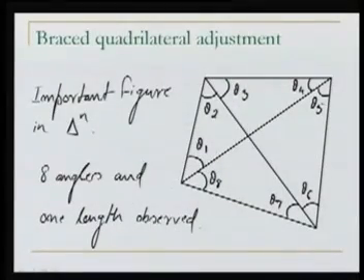Now we will see the adjustment of a base quadrilateral. We know what a base quadrilateral is; we have seen it when talking about triangulation, and we will do this adjustment by the condition equation method. Now a base quadrilateral, as you can see here, has A, B, C and D. These are the triangulation stations, and from these stations, we know one of the lines. This line is known from a previous triangulation, or it has been measured. So this is known to us.